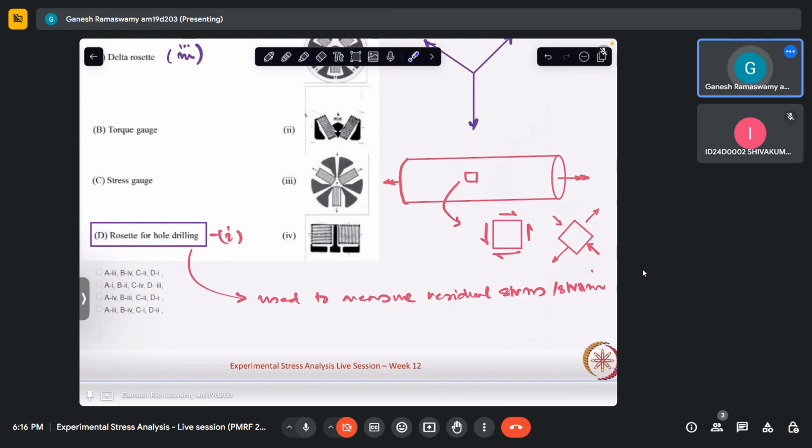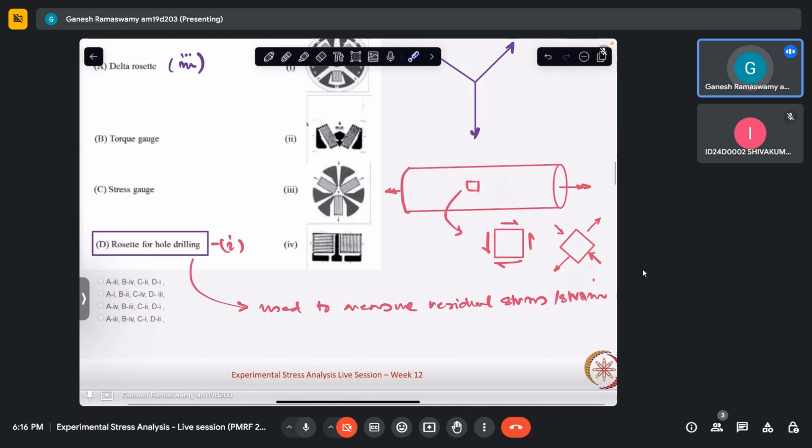So if we can measure the principal stresses or the principal strain, so to speak, along two orthogonal directions, we can actually populate the entire stress tensor in the case of this torsion. So we can see here that here the grid is aligned this way and the other grid is aligned like that. So this actually gives us a measure of the torque. So if we were to map it based on this, we will get A as the option.